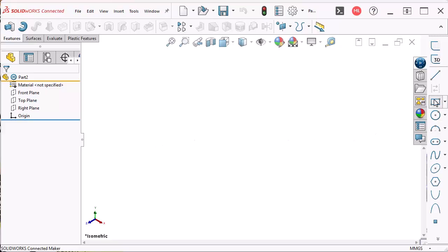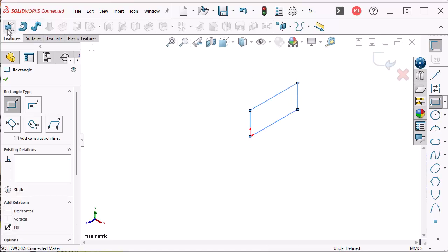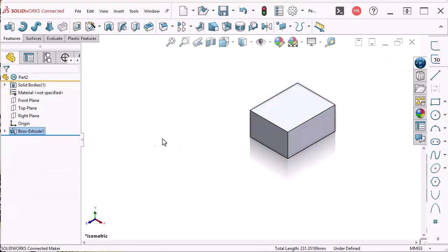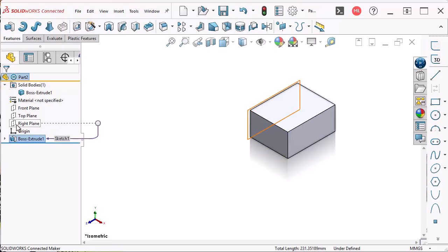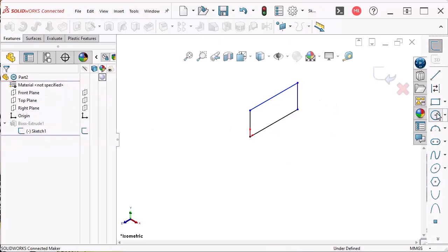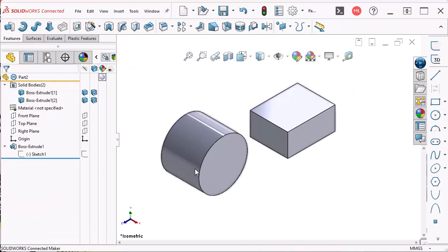If we are to create just a single extrusion and extrude this, doesn't matter what feature we use really. Okay, we've got a single solid body. And I'm going to press F8 here to get my display panel to show up. That's a single solid body. Now I'll go back to the sketch and I'll create another sketch that goes like this. This is actually all in the same sketch, but we have two separate enclosed areas. And when we extrude those, we get two separate enclosed volumes.